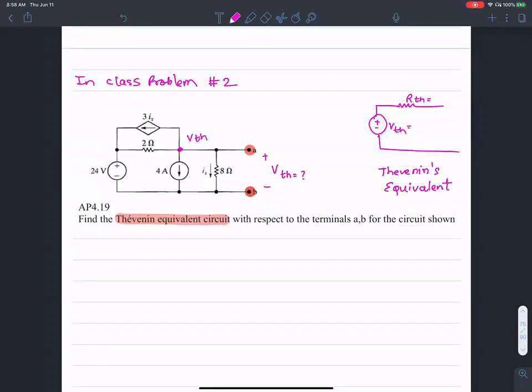If I think of this as a ground, if I had a resistance down here, then this would be a different value. Then the voltage dropped across this would have to add to the voltage dropped across that to give me a node value for that guy. But because there is no resistance here, I can assume that this guy is also going to be V Thevenin.